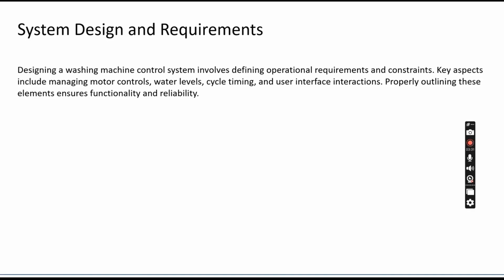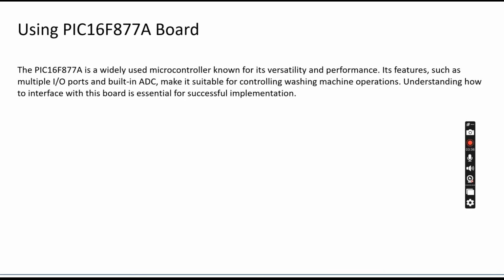Let us dive into how we implement these using embedded C, MPLab, and Proteus. So, using Proteus, let us take a simple implementation. The PIC16F877A board is connected to a water level sensor on an analog input pin and controls a motor and pump where relays would be. This code simulates the water level using the ADC. It starts the motor. If the water level is sufficient, it runs a 5-second wash cycle